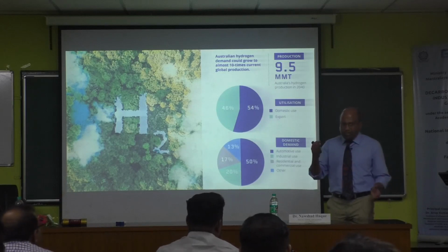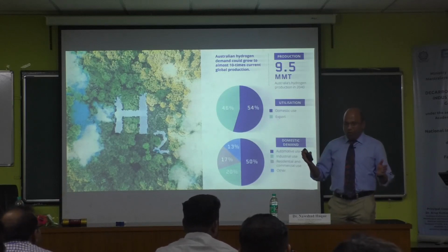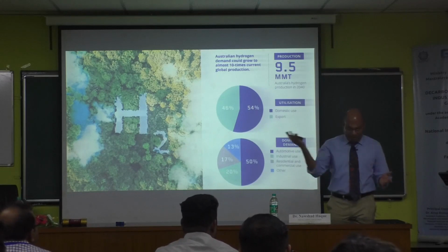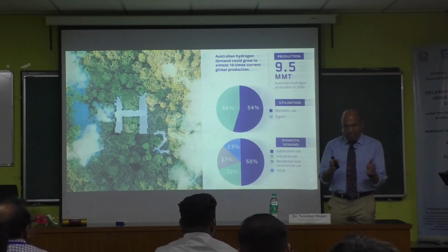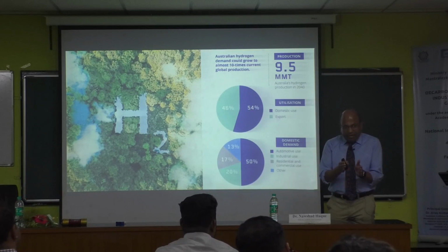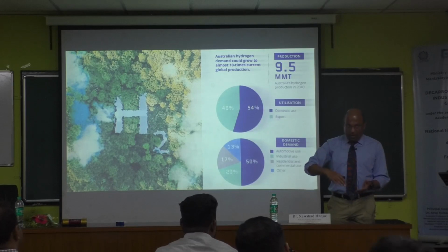Gas export, nobody could think of. But now, what we do is compress. So CNG, we have got CNG vehicles, right? So you can compress so that you can make the density high and also the energy content high, and then you liquefy it. How do you liquefy? Minus 152 or 153 degrees. If you go that low, then you will make liquid.